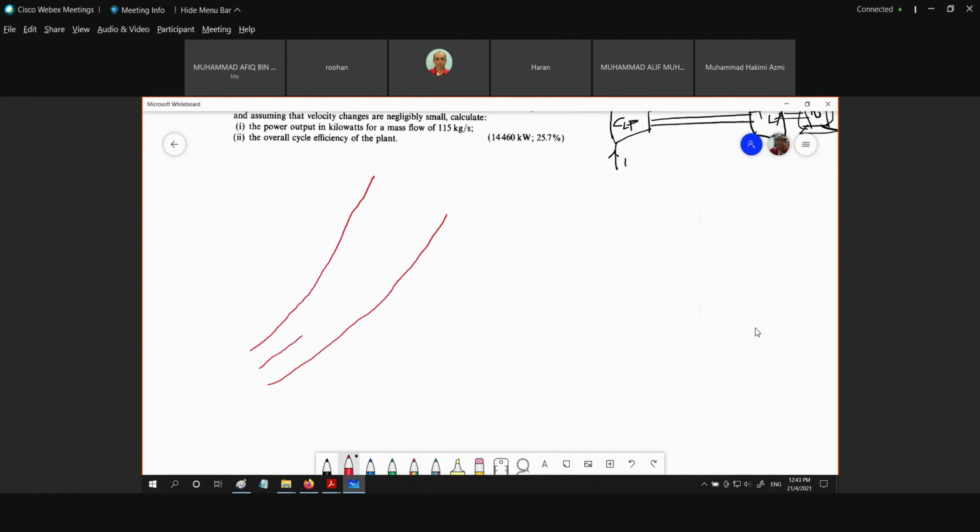Okay. Let me see, in this case, I don't connect the intermediate pressure of the compressor and also the turbine because there is no info saying that it's equal in terms of pressure ratio. But in the previous example, for the test 2 question, it was said that the 4 main components, which are the compressors and the turbine, have the same pressure ratio. But in this case, there's no description about that.